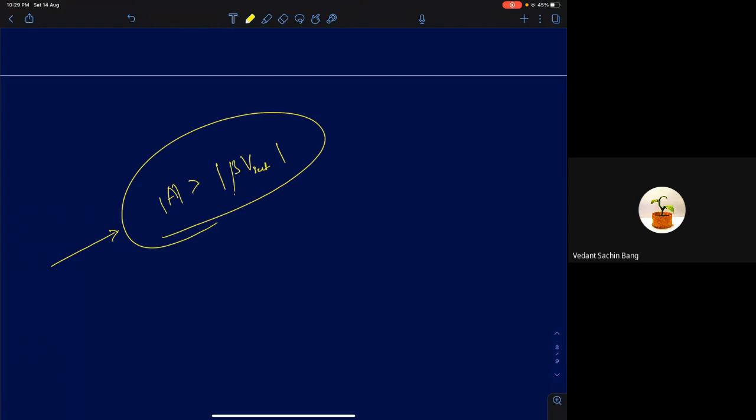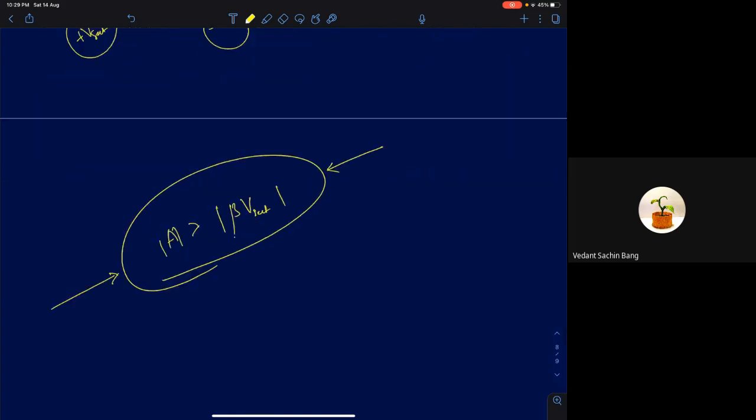But at this point, operational amplifiers can serve as very good Schmitt triggers for lower frequencies, provided you meet certain conditions. The amplitude should be greater than plus beta Vsat, and you will get a 50% duty cycle if your positive and negative voltage levels are the same. Okay, so that's it. We'll discuss more about the applications of op amps in the upcoming lectures.